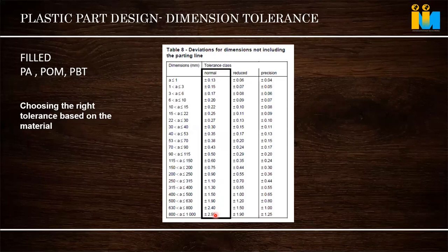But for crystalline material, keep in mind, give as generous a tolerance as far as possible. Otherwise, it is very difficult to prove. Tool cost may go up. Even the mold wears out after some run. Then again there is a problem. So wherever possible in the product design, maximum we have to give as per the requirement.